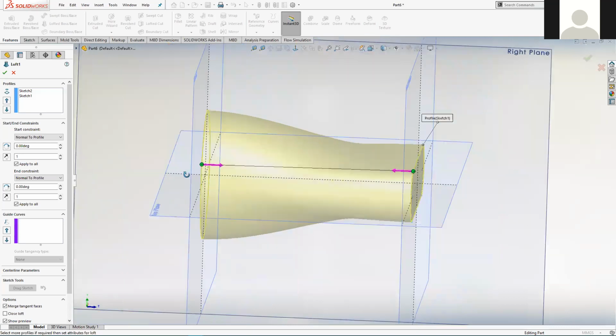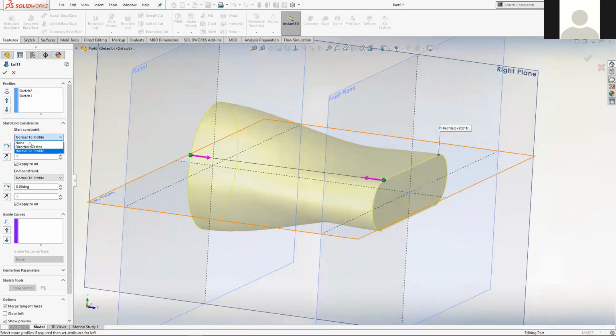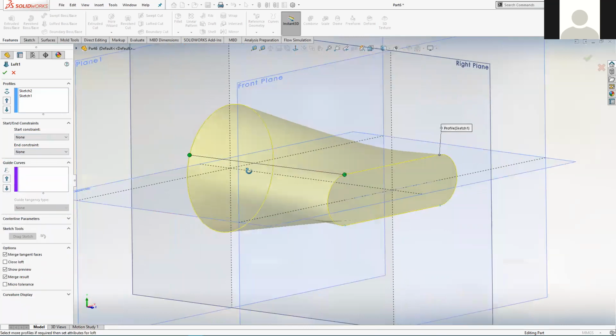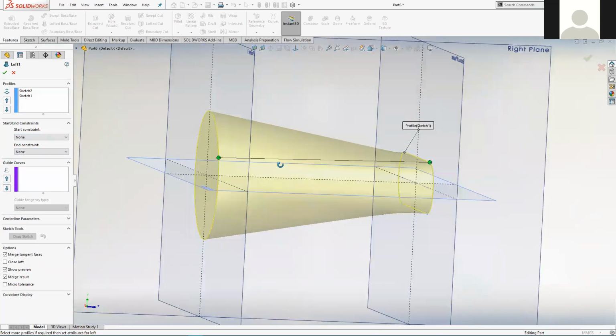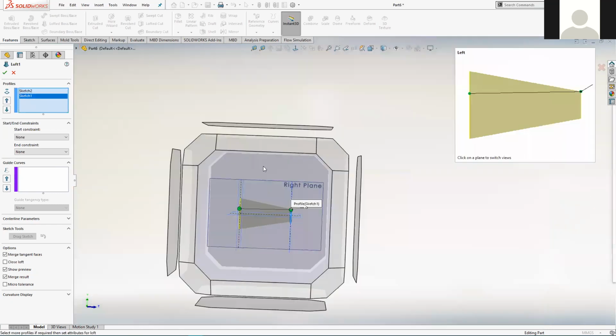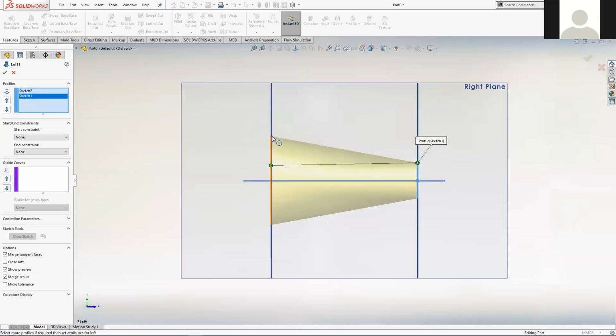And the reason that we're going to assume that is because it gives us an opportunity to play around with these options within the loft. So initially, any lofted shape that you create, any lofted feature, will transition between the various loft profiles as efficiently as it can. And in our case, you can see from a perfect side view, that translates as just a straight line.